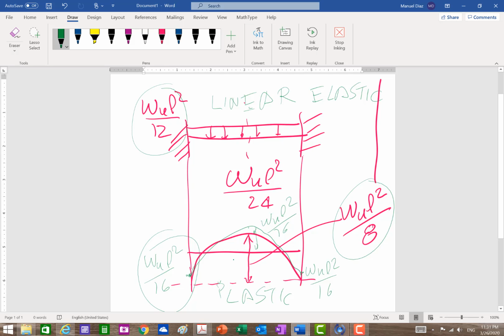By mechanism, I mean that now this one is a plastic hinge, that one is a plastic hinge, this one is a plastic hinge. So now your beam has a hinge, and a hinge. Well, three hinges will make a mechanism, right? It will simply break like this, right? Because now it has those three hinges. So that's the maximum you can make it work. But this is sort of an idea of what a redistribution is.